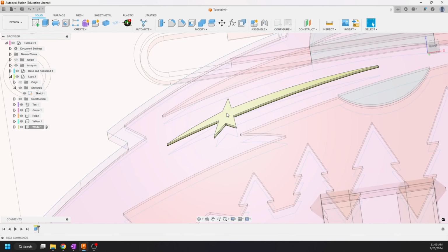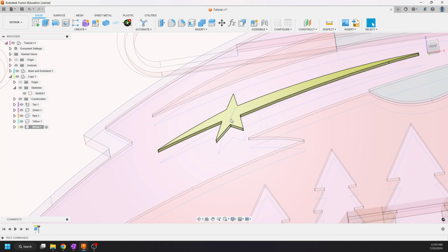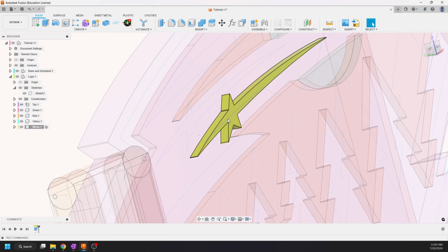So you can either do maybe a triangle shaped pin, or what I generally do with these is I will just make a sketch on the back side of a complex item. I'll do an offset, and then that offset can be extruded. I'll show you what I mean.